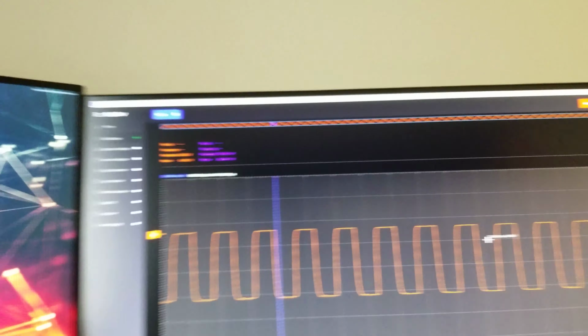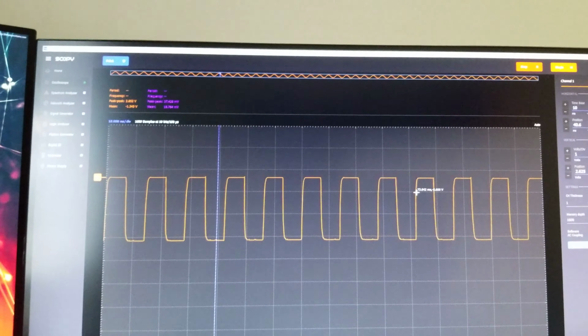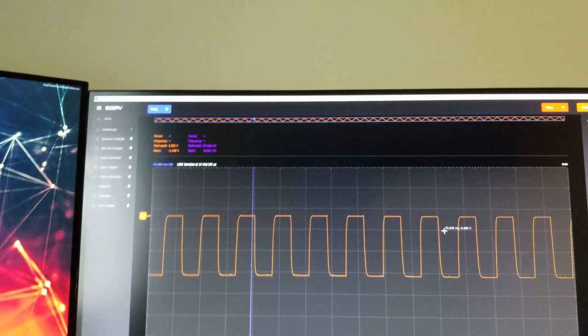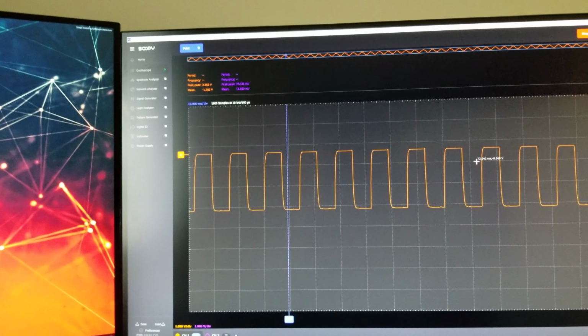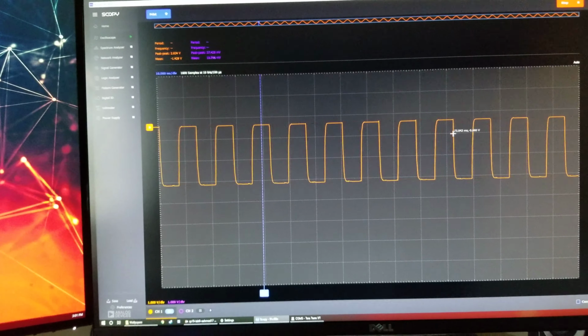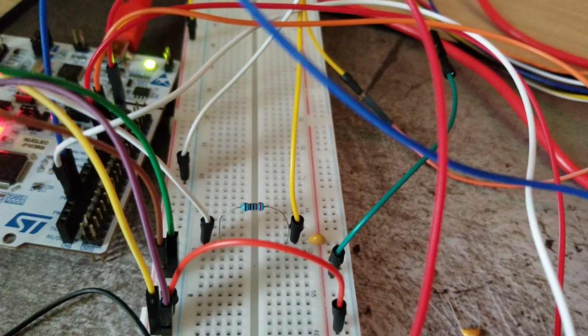I think nominally you would want a more robust RC circuit for the type of charging and discharging that needs to happen. I'm not particularly good with the analog stuff that's required to figure out exactly how that goes. I tried a few different types of resistors, and I put resistors in series and stuff like that to try and get what looked best. And this RC circuit was giving me the best response, so that's what I just stuck with.